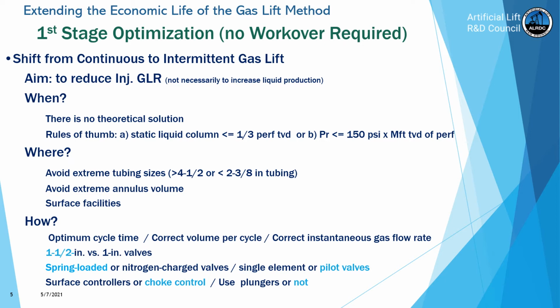So, but surface controllers have a huge advantage, and if the system is not that big, you might be able to use a surface controller, because with a surface controller you control not only the cycle time, by keeping the controller closed, lowering or increasing the time the controller is closed, but also you can fine-tune the volume that you pass per cycle by keeping the controller open for as long as is necessary.